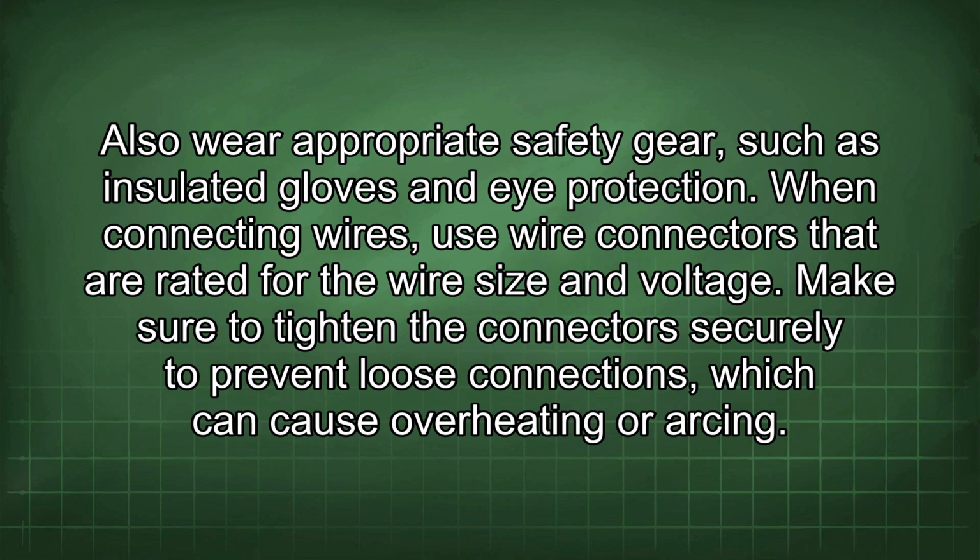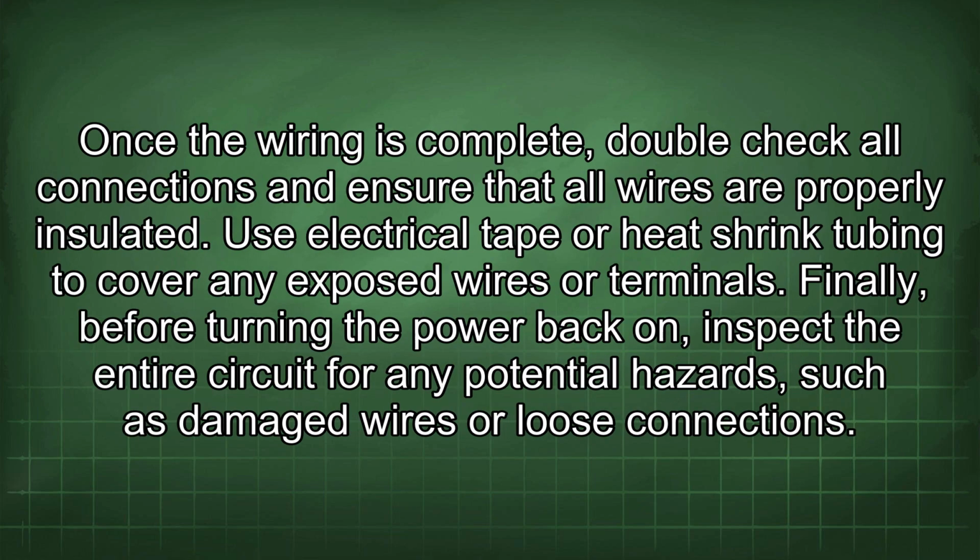When connecting wires, use wire connectors that are rated for the wire size and voltage. Make sure to tighten the connectors securely to prevent loose connections, which can cause overheating or arcing. Once the wiring is complete, double-check all connections and ensure that all wires are properly insulated. Use electrical tape or heat shrink tubing to cover any exposed wires or terminals.